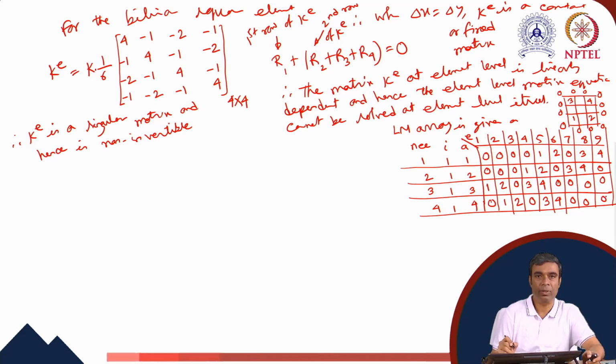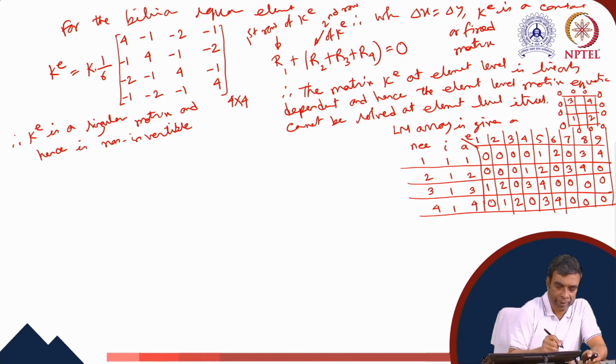Now, let us construct the assembled matrix equation. First, we construct the assembled matrix capital K. The components are K11 through K44. This will be a 4 by 4 matrix with 4 global unknowns. So the first term is K11.